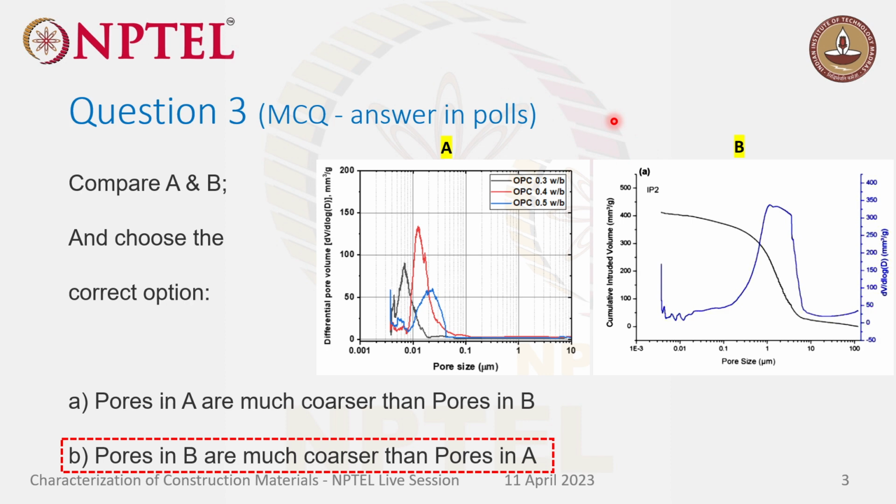So they can take the brick unit and put a repair mortar, and they can put the same brick, or if the brick is also damaged, they can put a new brick and do the repair work. Normally, historic structures have a lime plaster which has coarser pores compared to a cement system. That's why if we use cement mortar on historic structures, the repair soon fails, because it is not compatible with the system and how it was actually constructed.